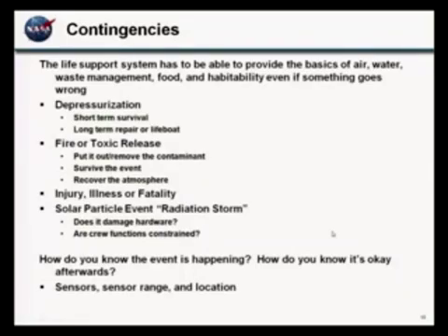But if you have a fire, there's going to be a lot of it, and it's going to be outside of the normal calibrated range of your sensor. It may ruin your sensor. Sometimes, depending on the technology, if it goes off range, it may flood it and take a while to come back. So then you start having to have a normal detection option, a contingency detection option, a post-contingency detection option, and it can get a little bit more complicated.